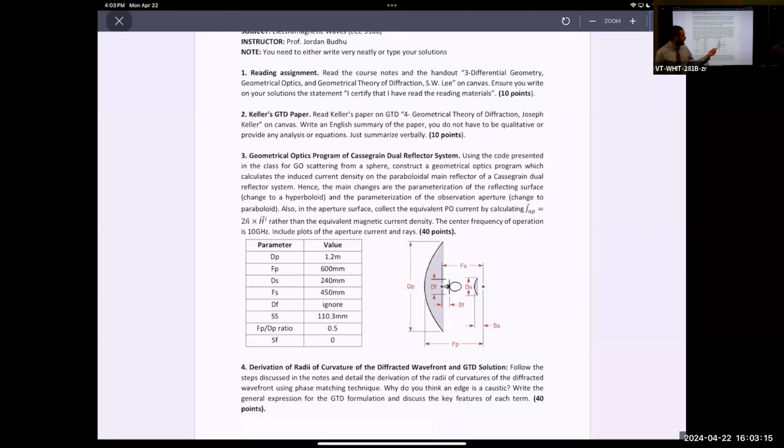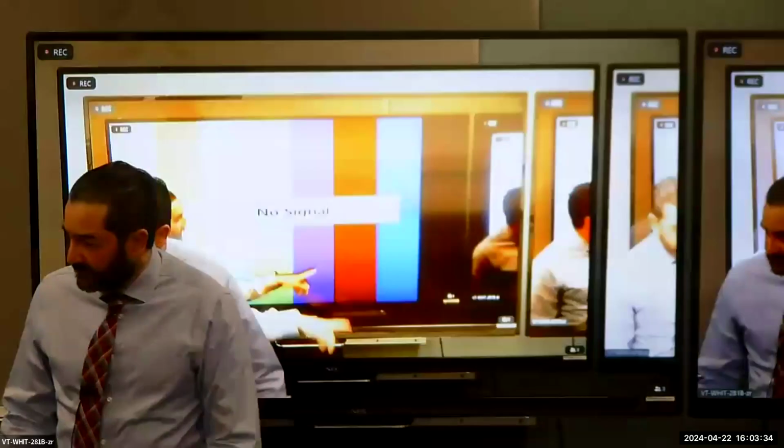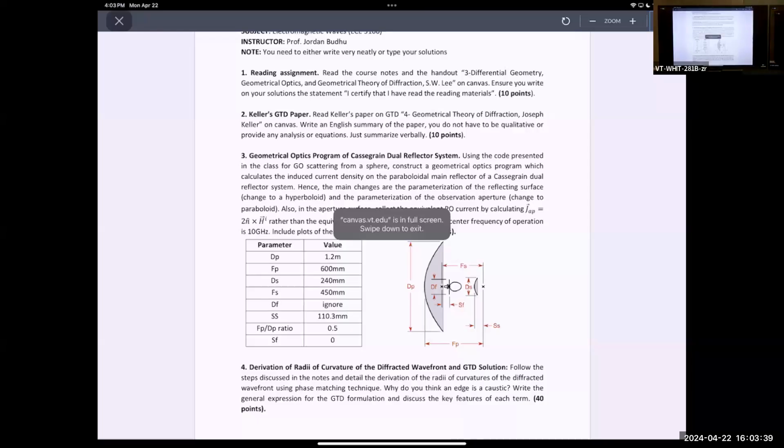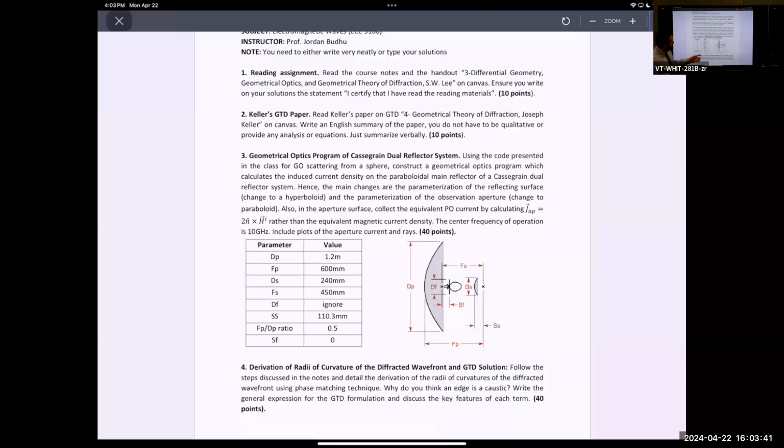Okay, so you want to align the foci of these 2 reflectors, and here you have the 2 foci of the hyperboloid, right? The feed goes at one of the foci, and the other focus is called the virtual focus, if you will. You take the paraboloid, and you place its focus at the virtual focus of the hyperboloid, right?